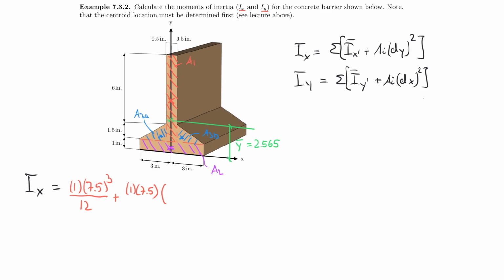But now the lever arm is what? The lever arm is the distance from the centroid of the individual shape to the centroid of the total shape. And so I will make my life easy, actually. I know that this here is 7.5 halves, right? So remember that I have this distance here, which is 7.5 over 2, which is equal to 3.75. So that 3.75 is also true on the bottom part. So I'm just going to now move from here all the way down, and then I subtract this part. That will make my life much easier than actually using a lot of brain power.